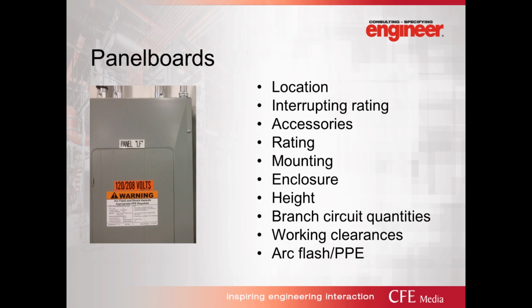The system can be either fully rated or series rated. In a series rated system, each device needs to be rated for the available fault current at its terminals. The advantage is that the equipment costs are lower, but the disadvantage is that you have to calculate the available fault current at each device's location in the system. Healthcare facilities typically require a fully rated system.